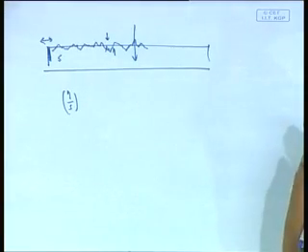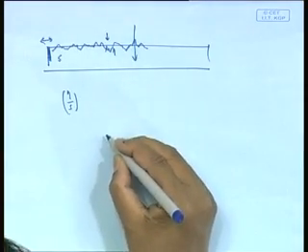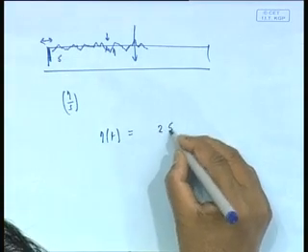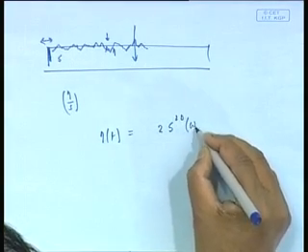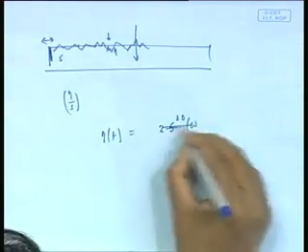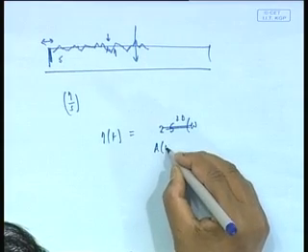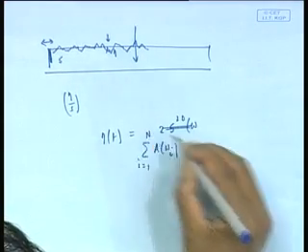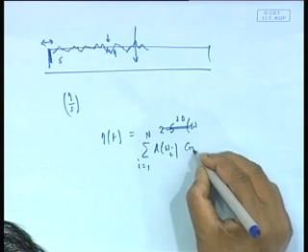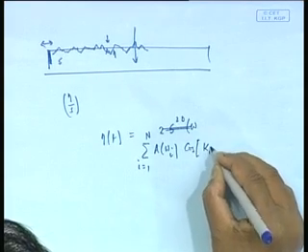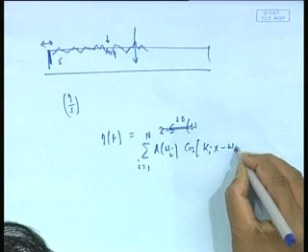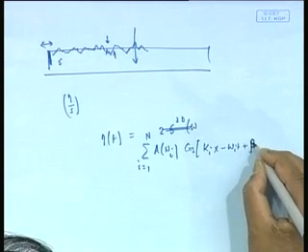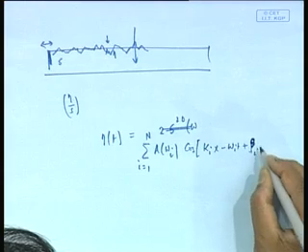So, what I said for 2D spectrum, I created that by simply saying eta t was equal to, well, let me put it the other way around, A omega I cos(k I x minus omega I t plus say some beta or theta, say beta, we call it beta I).